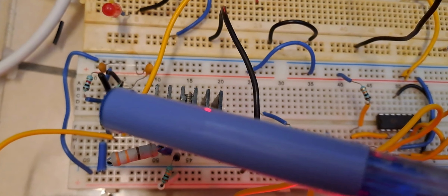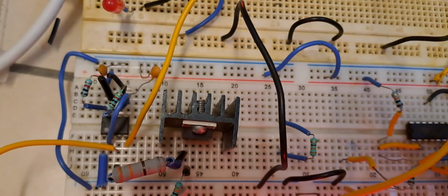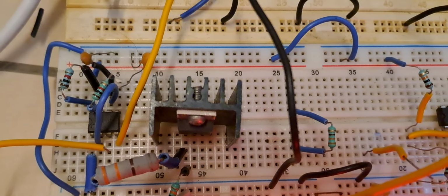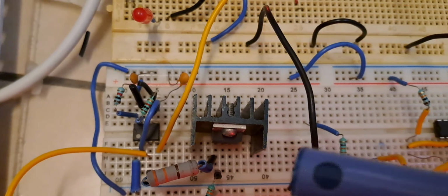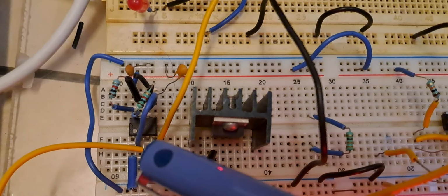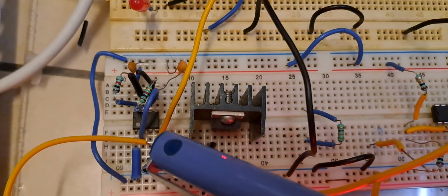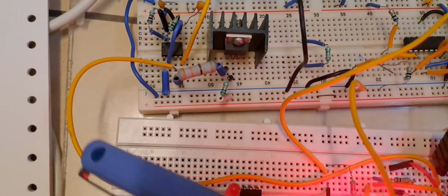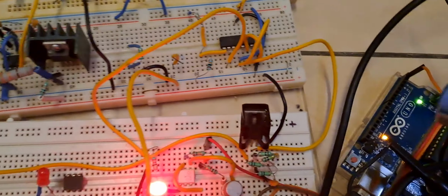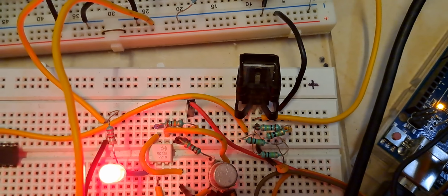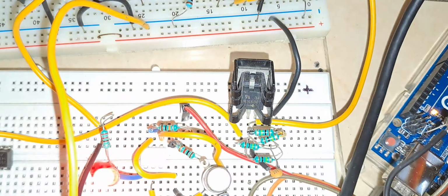The oscillator is designed to generate a frequency of 48 kHz. The output of this oscillator is coming from pin number 3 of the 555 timer IC. So the 555 timer IC pin number 3 is the modulated signal. This modulated signal is coming here and it is fed to this envelope detector. As you can see, this is the envelope detector.